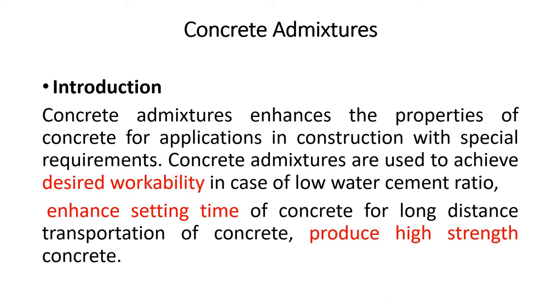Concrete admixtures enhance the properties of concrete for applications in construction with special requirements. They are used to achieve desired workability in case of low water-cement ratio, enhance setting time of concrete for long-distance transportation of concrete, and produce high strength concrete.